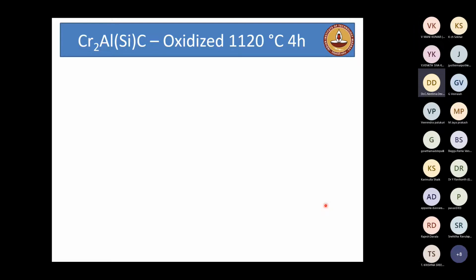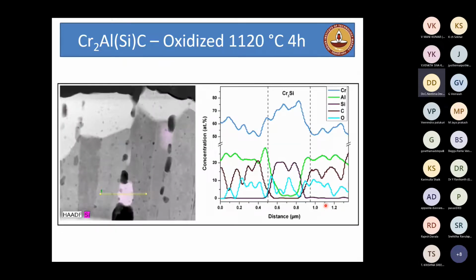If we now try to examine what is the silicon enrichment, if you take a one-dimensional profile, then you can see that the MAX phase still has some amount of silicon which is present on the V-shaped defect before oxidation. But after annealing leading to oxidation, the V-shaped segregated silicon has now coarsened into a type of a chromium silicon precipitate. It's no longer elongated as in the as deposited condition of an atom probe that you have seen, but now it's more like a globular precipitate of chromium silicon enrichment. And now from the stoichiometry, you can say this is again a chromium 3 silicon stoichiometric precipitate that is sitting on a grain boundary. But how do we now statistically know which of these precipitates are chromium silicon carbide?